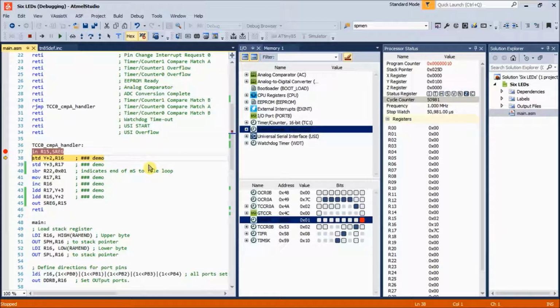If you're writing to memory, you usually put the data that you want to write into memory into registers 0 and 1. And the reason for that is there are some of the memory handling instructions that will only use those two registers. For anything that needs immediate values, you have to use registers above 16.